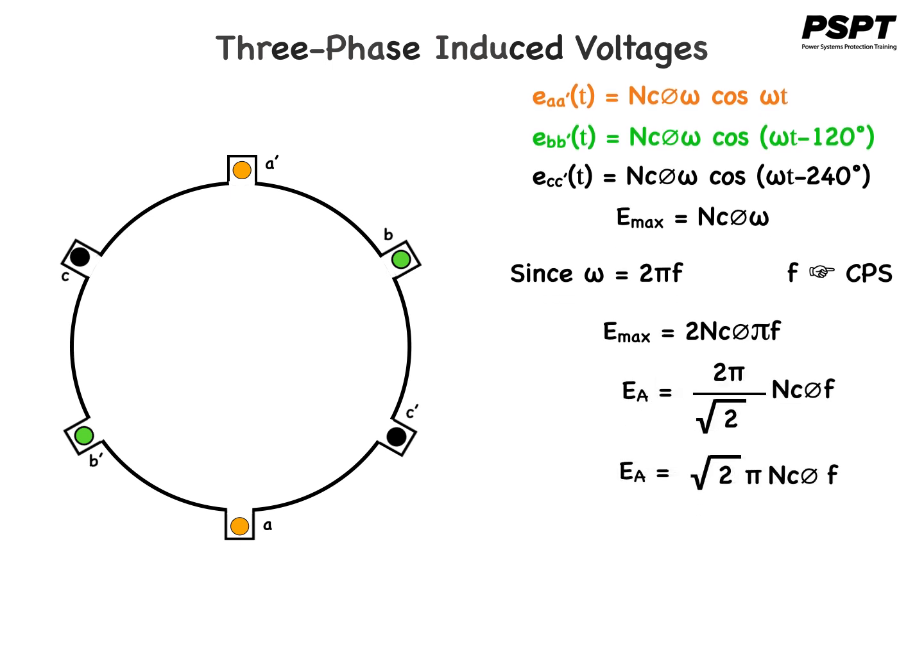Let's remove the rotor from our diagram momentarily. It's still there, it's just that I want to concentrate on the stator windings for the moment. The RMS voltage at the terminals of this machine will depend on whether the stator is connected Y or delta. If the machine is Y connected, the generator coils will be connected and will look like this.